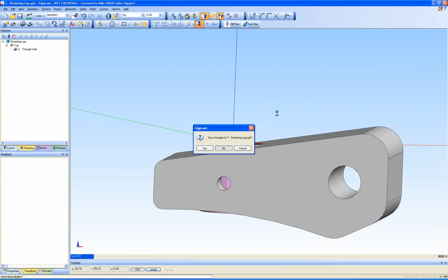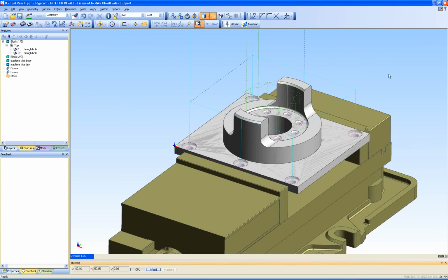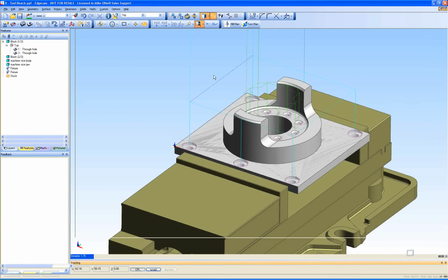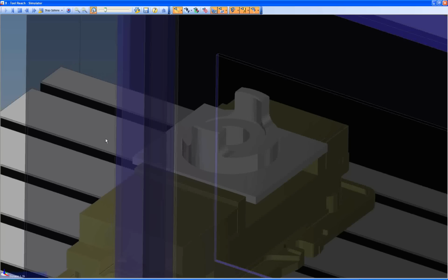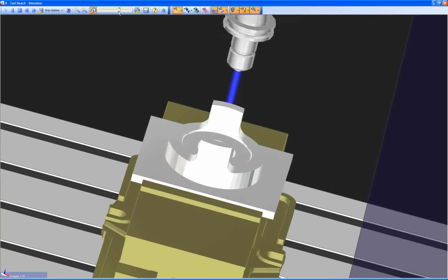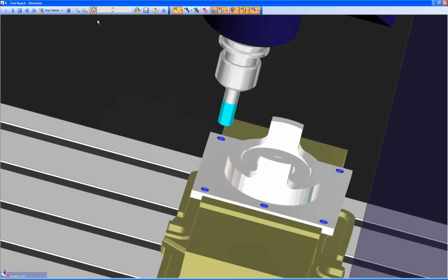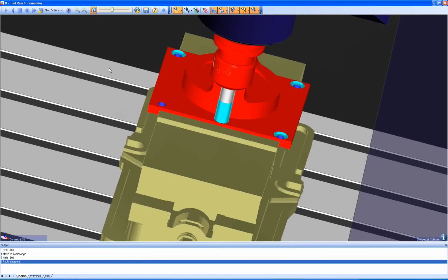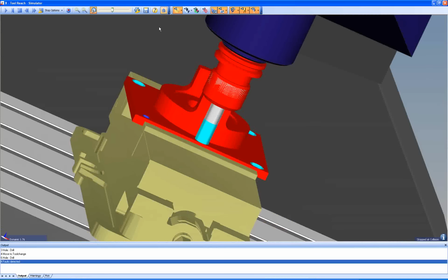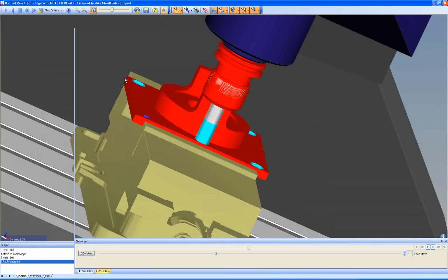Another little item is to do with the tool reach inside Edgecam Tool Store. We understand and know that there is an influence over the tool reach. That's to do with the offset amount. Well, this is a typical symptom. We're furiously testing a part, we're simulating, we take it into simulator, we discover that we have, unfortunately, a collision. And of course this collision is being caused by the tool not, there we go, we can see the clash now. We can see that this tool needs to be pulled further out. And of course that is quite simple and quite straightforward and normal inside Edgecam.